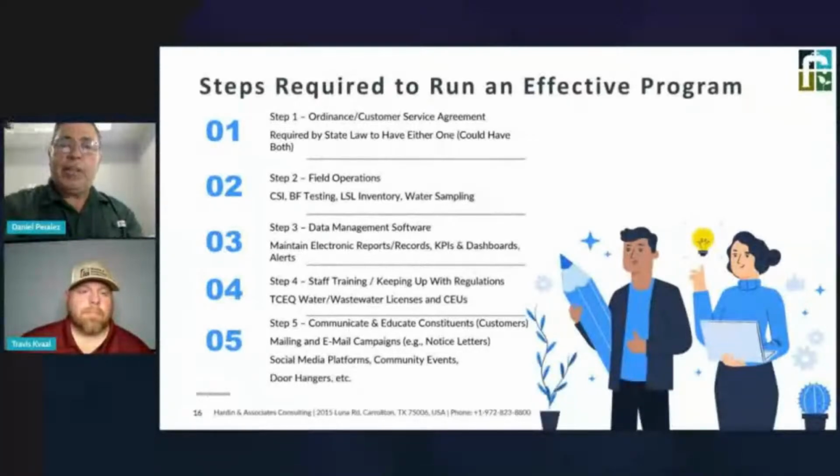The service agreement. What are the service agreements? The service agreements just helps with the enforcement part. It gives us access into the customer's private distribution system for us to be able to enforce the installation of backflow prevention assemblies and have them tested on an annual basis.